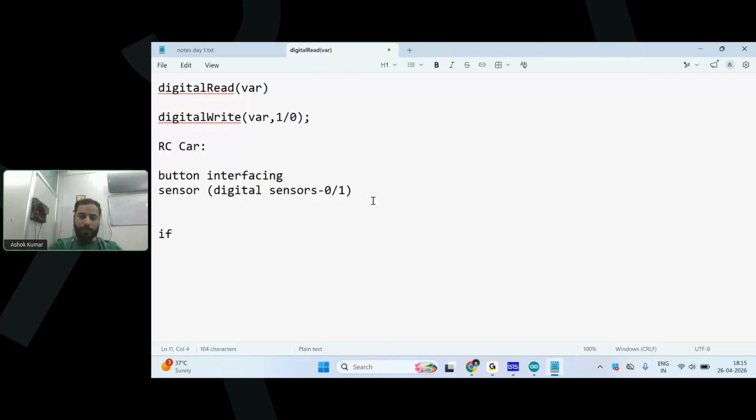So how we use if else in this embedded C++, let's try to understand that syntax first, then we'll come back to the main program. So if condition 1, then we start the code and write our statement 1, right? If you have only one condition in your program, you can write it this way. If your condition is true, then it has to run this statement. But suppose you have two conditions, how can you write it? If condition 1, statement 1, and then else if condition 2, and then statement 2.